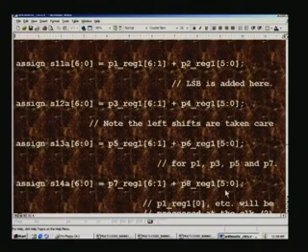Now in the first stage, we are taking only the LSBs, half the total number of partial products. This is the very first line of the partial products we had, and we also mentioned that the 0 need not be added initially, because we can straight away put that particular result after doing all the additions. That is why 0 does not come here.